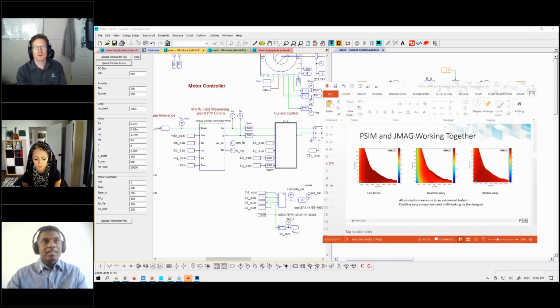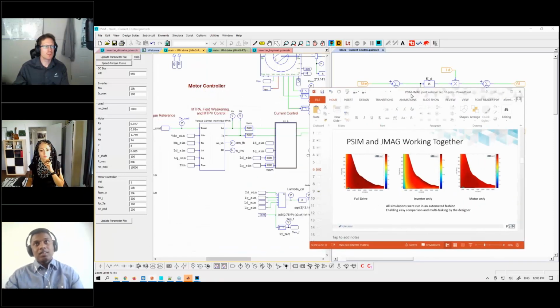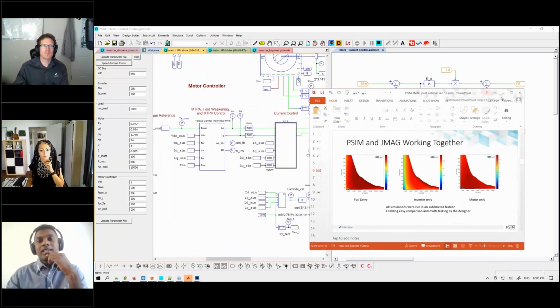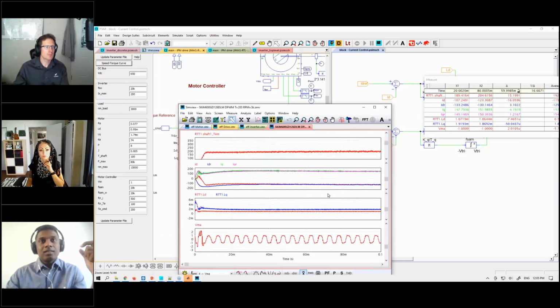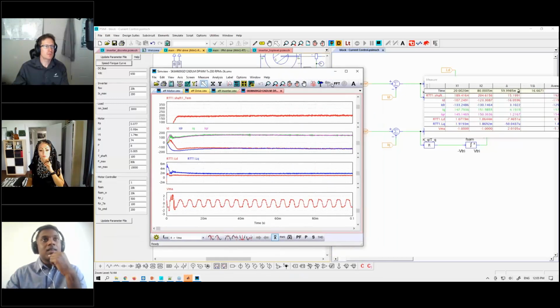Basically, if the finite element inductances are off from the measured values, what do we do about it? You can import or export CSV files, but that's more on the performance itself, not the inductance values. To change the inductance table, you need to go back into the JMAG RT library manager and change the source file from there.